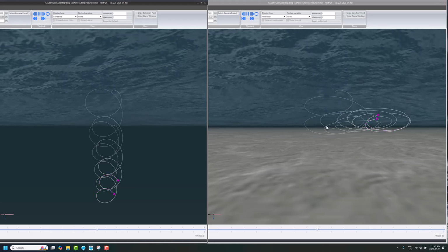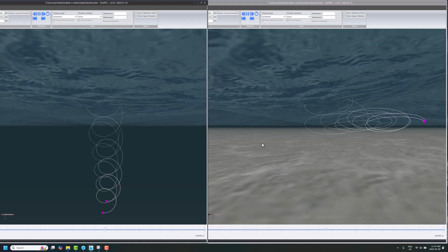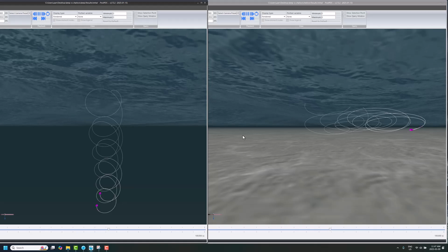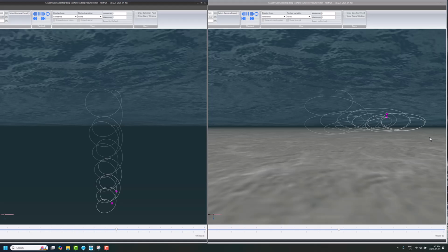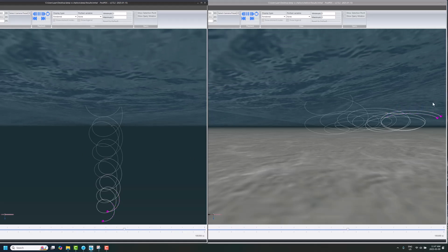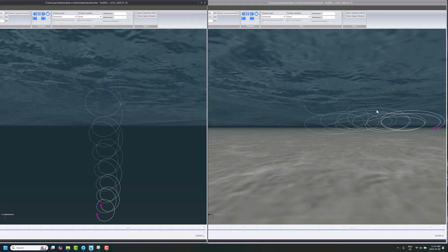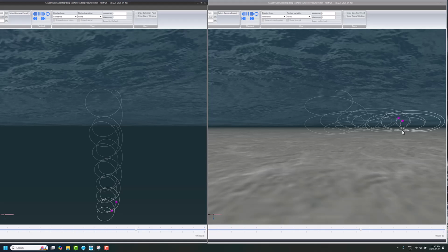So why does that matter? If you have a mooring in shallower water conditions, you could expect to see quite a big amplification of that back and forth drag loading and dynamics on the mooring. So it's just something to be aware of that gives you a bit more intuition about how these kinds of systems might behave, whether it's a mooring, a vehicle, or a floating structure.